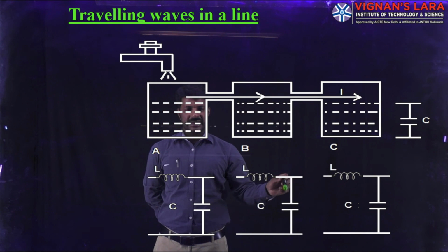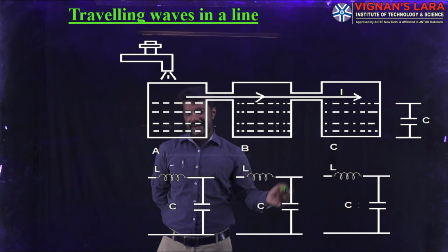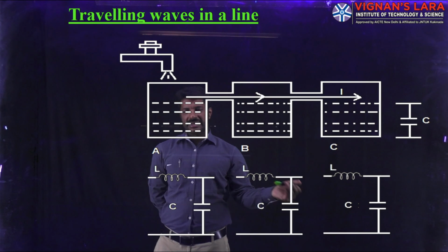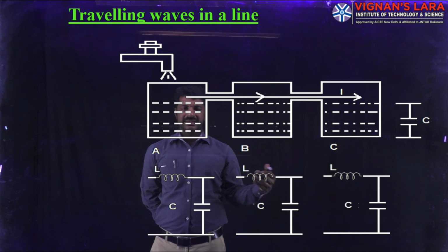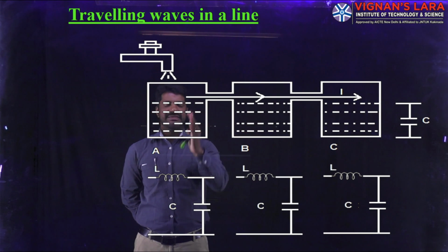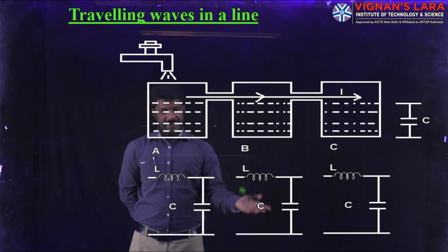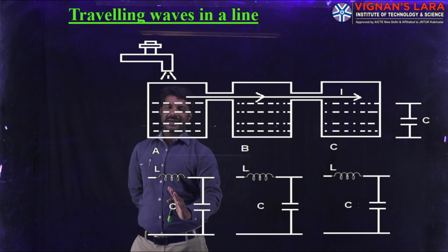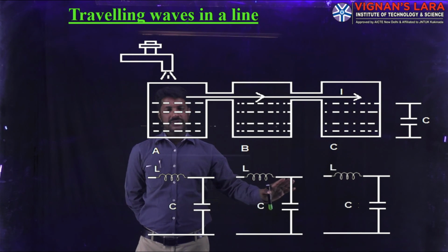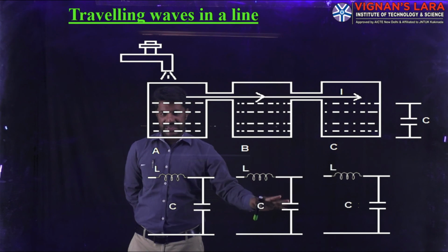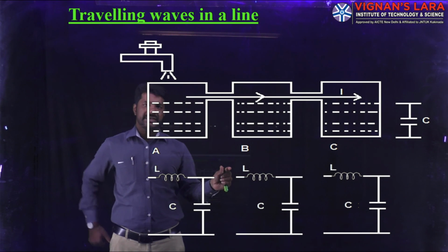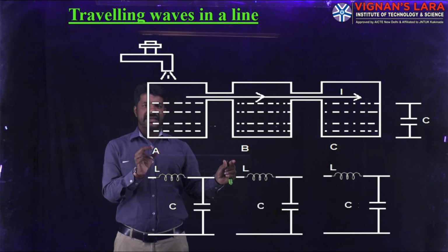If any obstacle happens at the middle points or at the end point, because of this obstacle, the charge flow called current, and also the voltages that are impressed step by step, will reflect back in a similar way to how the water turned back. Here also, the voltage wave or the current wave traveling in the forward direction will move smoothly until there is some disturbance on the transmission line, like a joint. What is a joint? The overhead transmission line has a certain characteristic impedance.